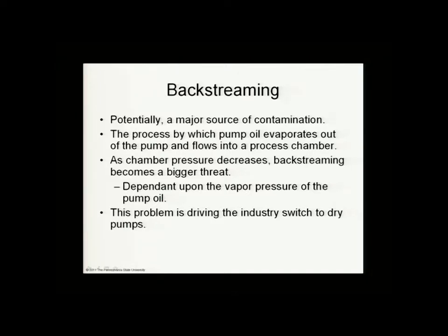That's not good. As the chamber pressure decreases, backstreaming becomes a bigger threat, dependent upon the vapor pressure of the pump oil, obviously, because that's the source of the molecules. Low vapor pressure, less of a problem.